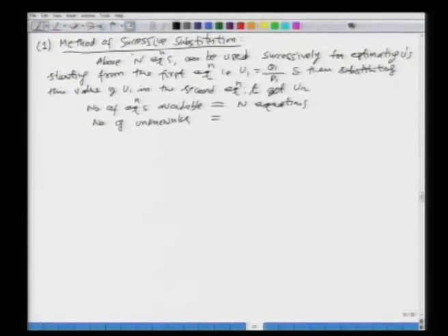What are the number of unit hydrograph ordinates? Well, that is n minus m plus 1. That means you have more number of equations than the unknowns. So, you have a system of linear equations, which is what is called overdetermined. What is an overdetermined system? When you have more number of equations than unknowns.